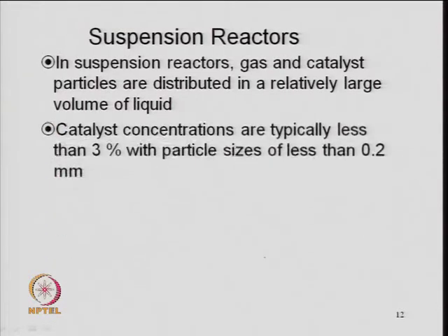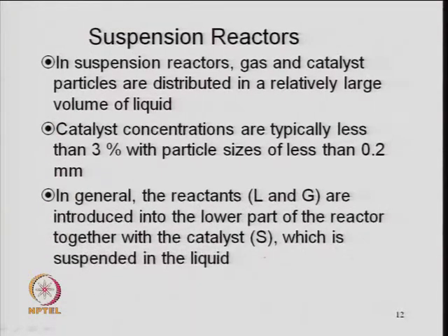And just briefly, before going into detail of the trickle bed reactor, I will talk about the suspension reactor also. The suspension reactor is again a kind of slurry type reactor, where the solid and liquid are together and some stirring is done to have a good contact between the liquid and solid. It depends on where diffusion or mass transfer is the problem, then these may be a better type of reactor.